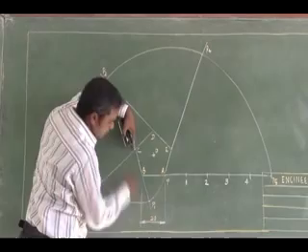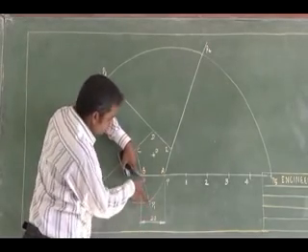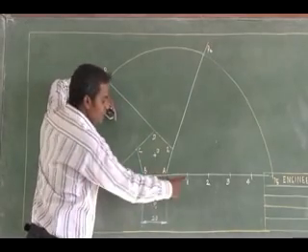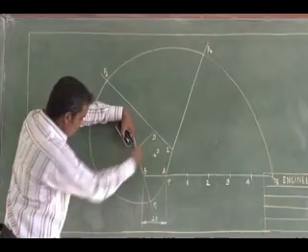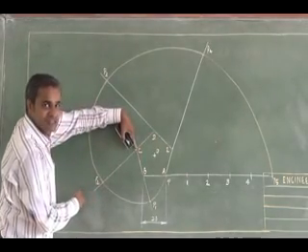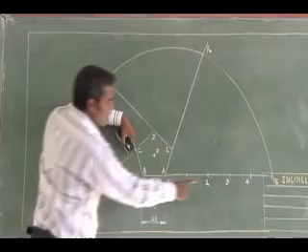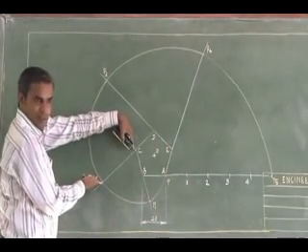The first division I can measure along the first tangent line drawn. The tangent line drawn is here. On the first tangent, point P1 will have a distance of the first segment, that is 20 mm. Then I have drawn a tangent line to the another side. From C, I mark P2 at the length of the second segment, that is 40.